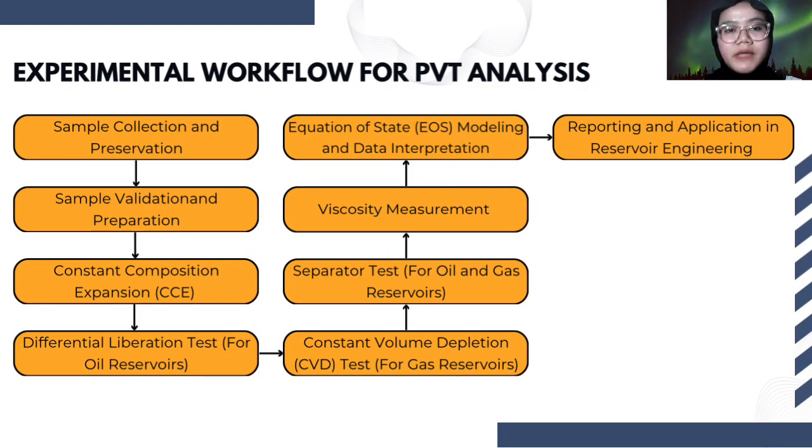Now, moving on to the experimental workflow for PVT analysis. PVT analysis is essential for understanding the behavior of reservoir fluids under different pressure and temperature conditions. The process consists of several key steps. The first one is sample collection and preservation, obtaining a representative fluid sample from the reservoir while maintaining its original pressure and temperature conditions. The second one is sample validation and preparation. The collected sample is then checked for contamination and prepared for testing.